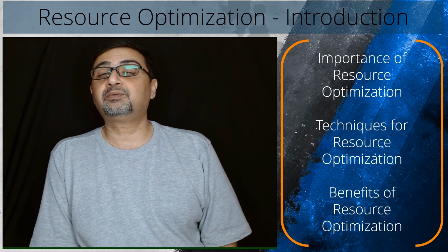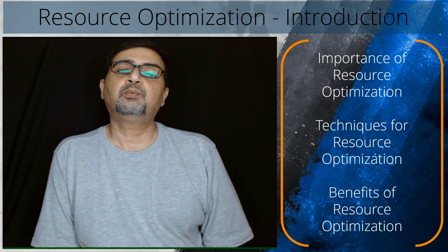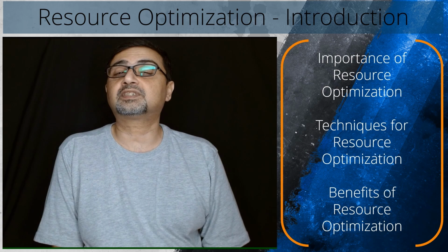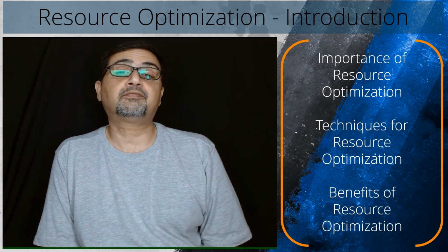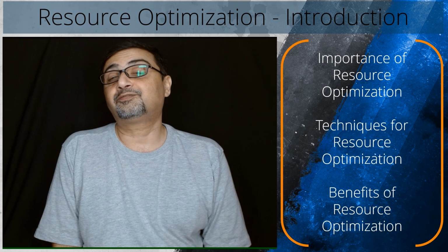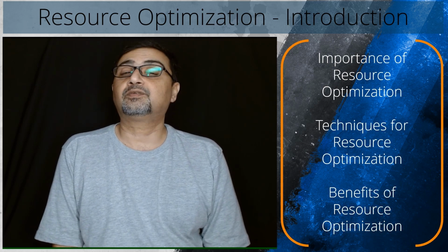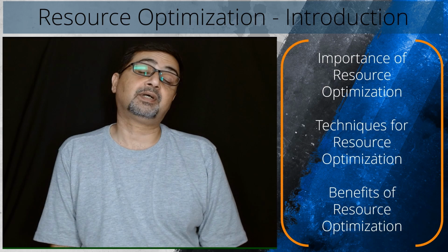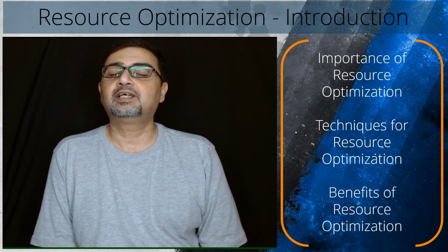To optimize resource allocation and level out resource demand, resource leveling techniques can be applied. In this case, we can adjust the start and end dates of certain non-critical activities that have flexibility within their float or slack time. For example, the finishing work might have some flexibility in its schedule without affecting the project's critical path. By redistributing the tasks within their float time, we can smoothen the resource demand and avoid resource overloads. The start date of the finishing work can be slightly delayed, allowing resources to be allocated to other critical activities during their peak demand. This leveling process ensures a more balanced and efficient utilization of resources throughout the project duration.